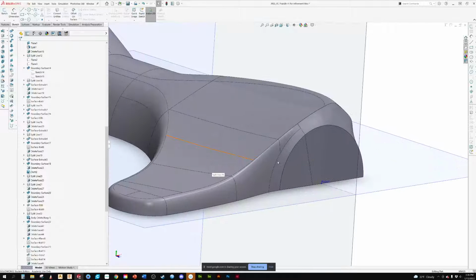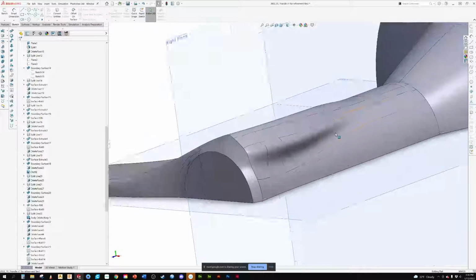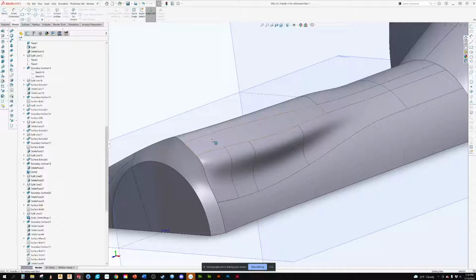But going in and doing this to get your radiuses right, or to add in a detail like this where you would cut something out and fill it back in with the surfaces, that's kind of what's referred to as patch modeling. Are there questions about that?